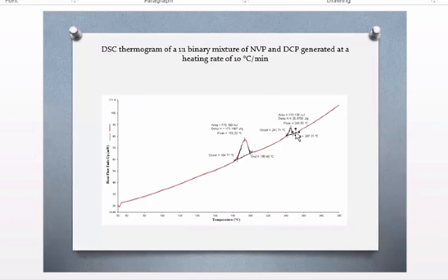But if you see this, the peak has significantly reduced in size. At the same time, it is no longer as narrow as it was initially. And if you check the peak, it is now occurring at 245.5 degrees Celsius from 250. From here, again, the principle is that if a peak is broad, then that material is existing as an amorphous substance.